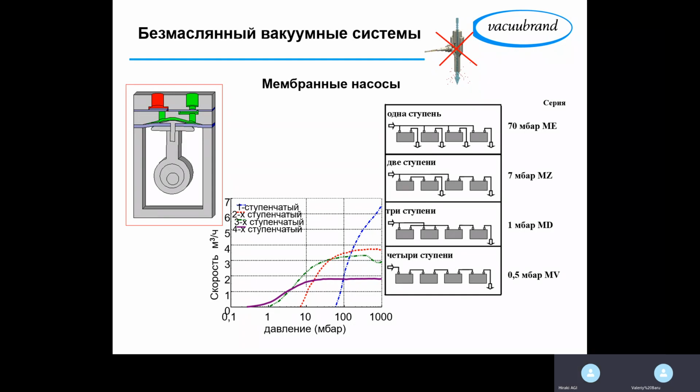That is why I've asked about 0.1 millibar, which would be definitely fine. And in this case, we can offer a rotary vane pump. 0.1 millibar is not an application for the membrane pump, because we will not be able to reach such a high vacuum with a membrane pump. Okay, so I see. Yeah, combination of actions.